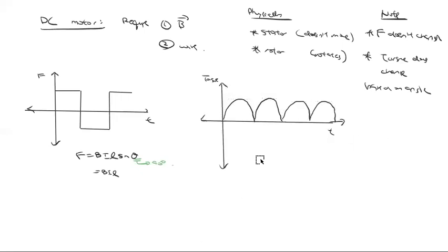So what ideally you want is a flat torque. This is ideal. Now, obviously, you don't have that, right? Before you turn the current around, you actually had a sine curve. Originally you had a sine curve. And that's not very helpful, because it just means your coil is going to turn 180 degrees and then back 180 degrees, and it's going to repeat that.